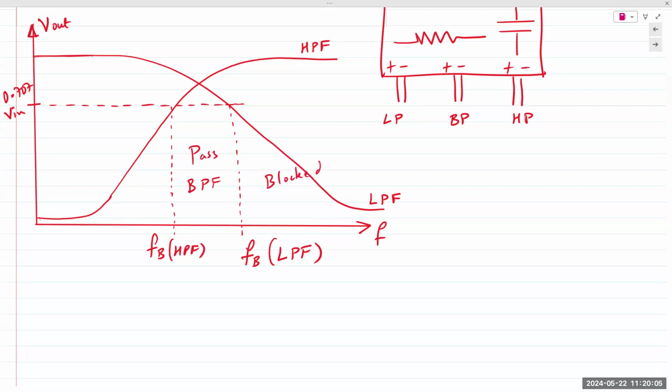Everything outside of this band is blocked by both filters working in tandem. Okay, so a band pass filter is a combination of a low pass and a high pass filter working together. Make sense? You have two cutoff frequencies, positioned some distance away from each other. There's a certain band of frequencies in the middle that is allowed to pass through, and you obtain a band pass filter.